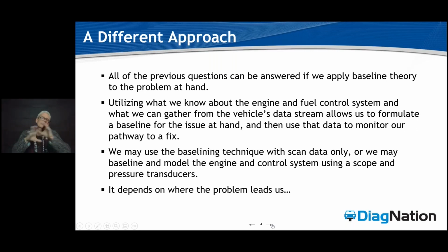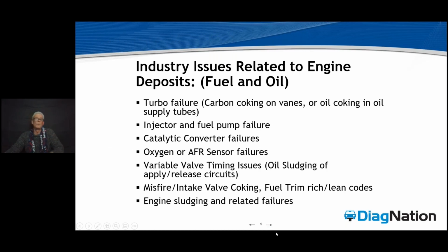So we can use the baselining technique with scan data only, or we may choose to employ an engine modeling physical testing system, such as a scope and a set of pressure transducers, to look at the dynamic in-cylinder waveform, check for valve leakage, do all kinds of cool stuff, which I'll cover in brief form here. But baselining is a very important thought.